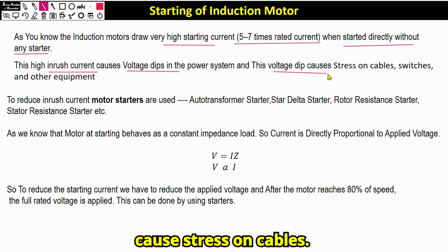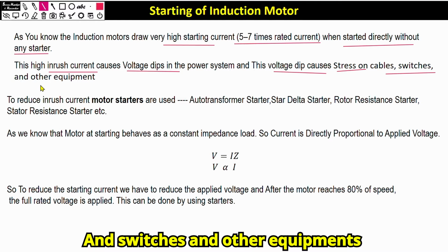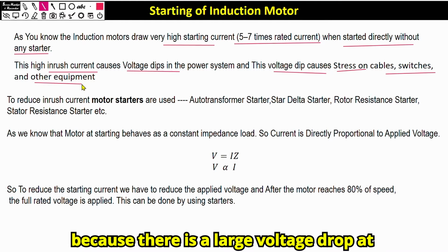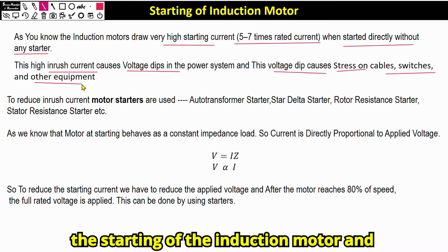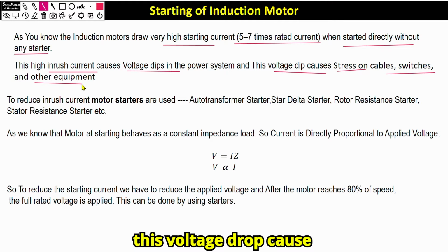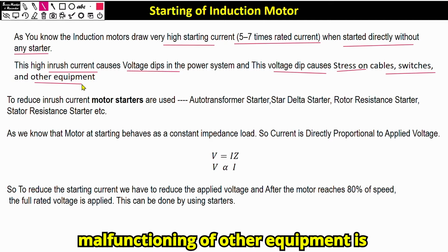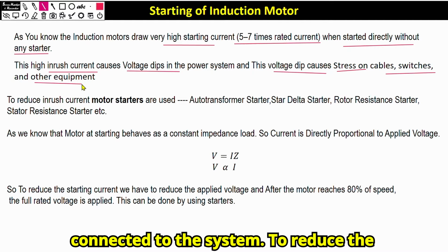These voltage dips cause stress on cables and switches and other equipments because there is a large voltage drop at the starting of the induction motor, and this voltage drop causes malfunctioning of other equipments connected to the system.